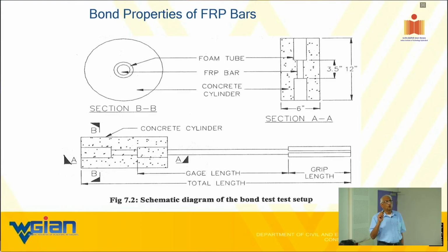The second most important reason why this quote-unquote uniform is not quite accurate is that in reality, when you do a beam bending type test to understand the bond, that beam has a bending component in addition to an axial component. We are not accounting for the bending component here because this is a pure axial.